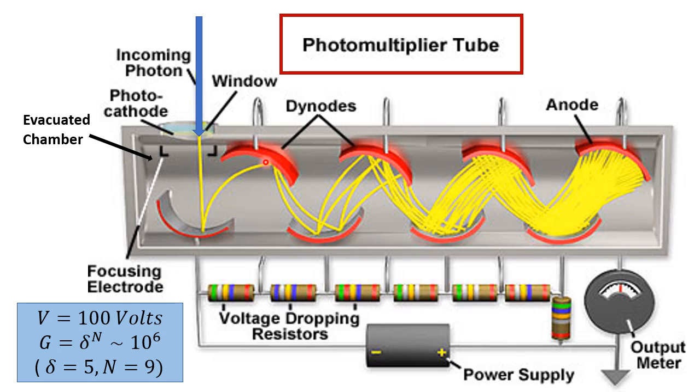These terminals inside are called dynodes. Okay. And each of those will release 5 more, because the potential difference is still about 100 volts between two. So you see there's a successive potential drop of 100 volts between these dynodes, and this process basically keeps multiplying. So extremely weak signals here actually result in an extremely large current pulse at the output.